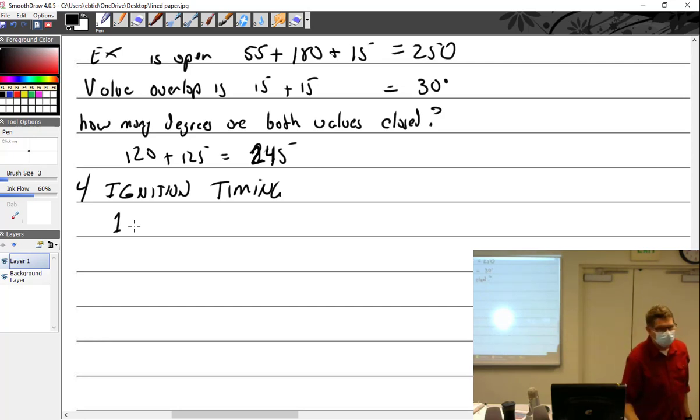And the 470s are all the big Continentals. When I say big bore Continental, so back up a little bit. You understand that there are two manufacturers of engines, and that's all that's left in piston engines. There's Lycoming and Continental. Lycoming is gray, Continental is gold. Lycoming does their starters external, and they put a ring gear around the front by the propeller, which has teeth around it, and a starter Bendix. It's very similar to what a car would do. Looks more car-ish.